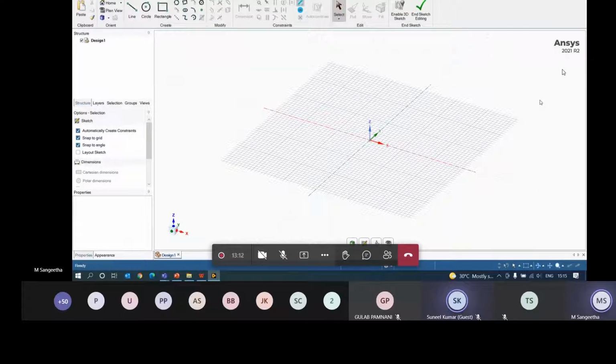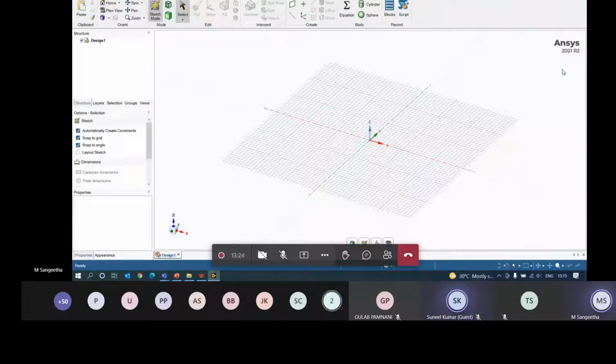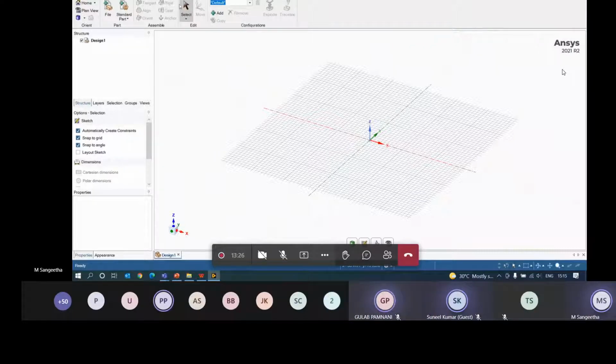Okay, so first let us understand where SpaceClaim can be an add-on advantage for us. The first advantage is 2D and 3D modeling: you can do sketching and modeling. Next, you can also work on assemblies. If someone is working on designing an aerofoil, those kinds of coordinate points can be imported as an input file, and you can create your geometry using coordinate points as well.